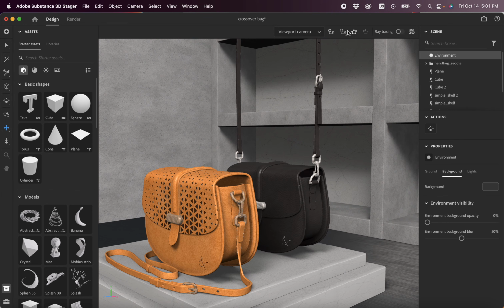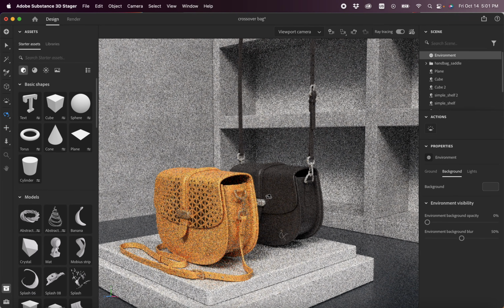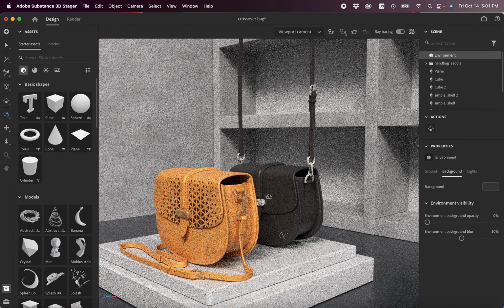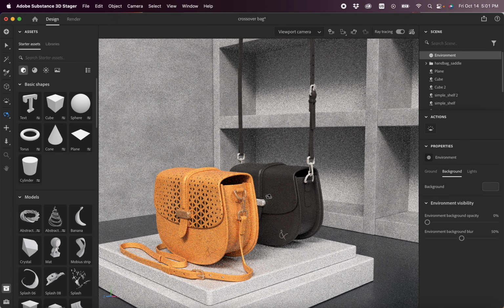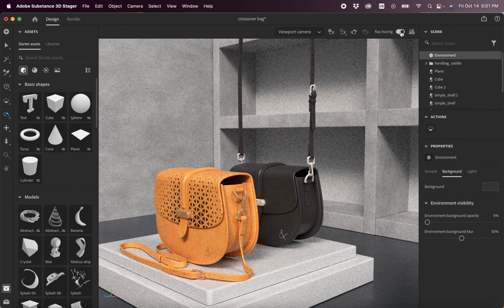in the Creative Cloud. This is where you can add certain cameras. You can turn on ray tracing, which essentially allows you to see the work after it'll be rendered, or as close to what it might look like after it's being rendered. Now, we usually turn off ray tracing while we're working because it really does slow down the process. So you really turn on ray tracing when you're trying to slow down and pause and see what the lighting effect is, what the model looks like, what the product or the general picture is, or how it's coming along essentially. Next we also have, I'm going to go ahead and turn it off.